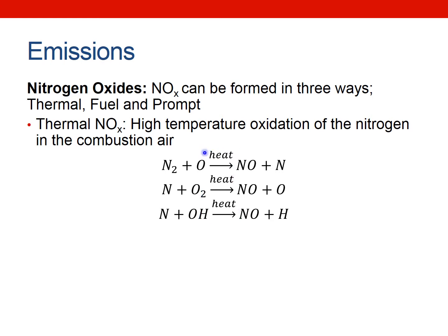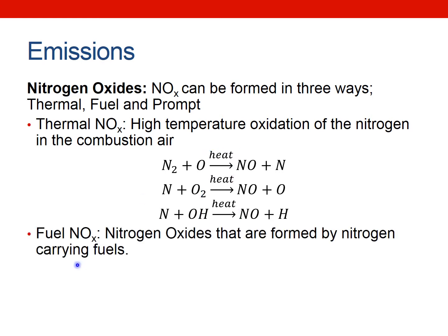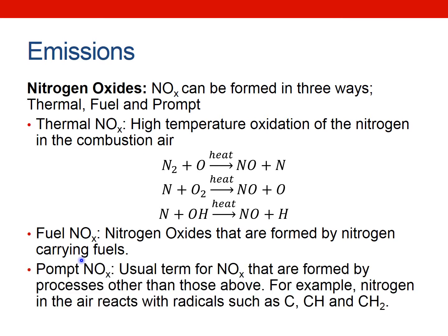That's how those ones are formed. Fuel NOx, well, that's fairly self-explanatory. These are nitrogen oxides that are formed by nitrogen-carrying fuels. So if you have nitrogen in your fuel, then that will react with the oxygen in the air, producing fuel NOx.